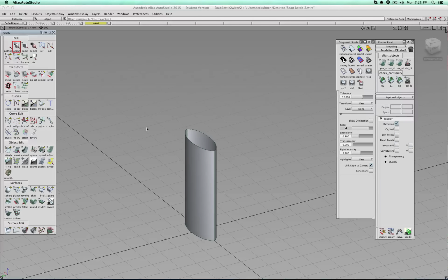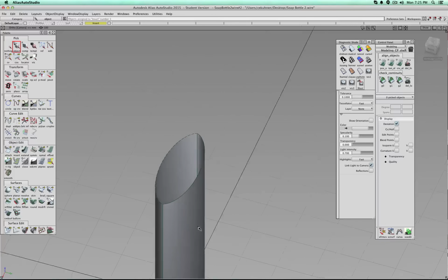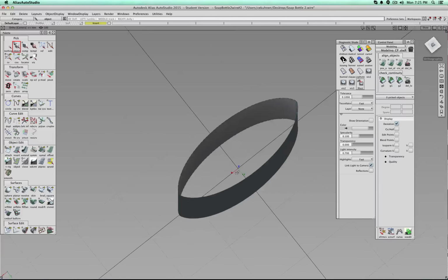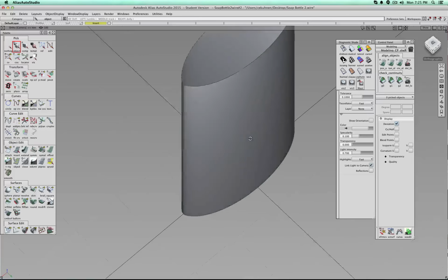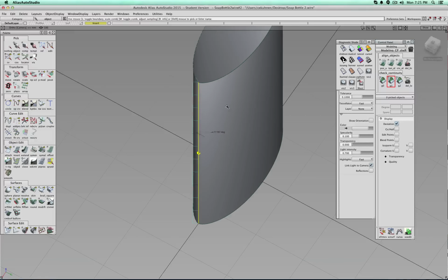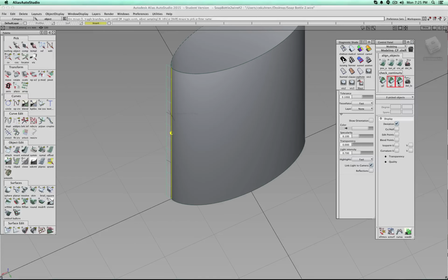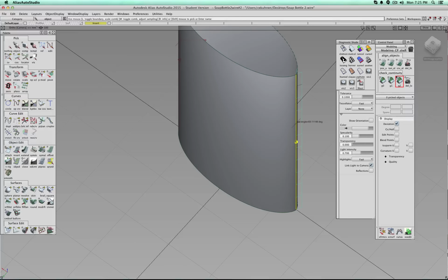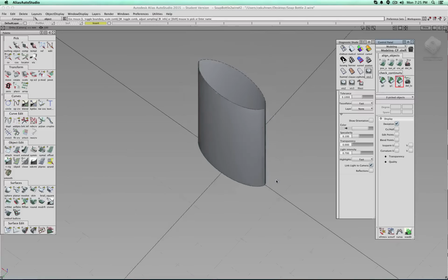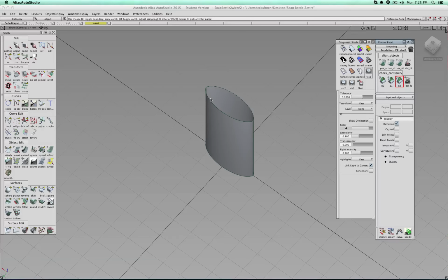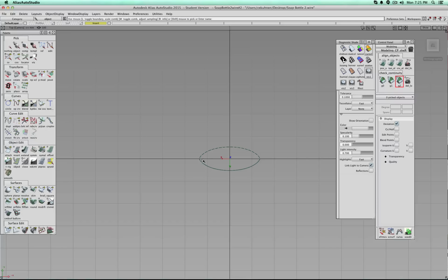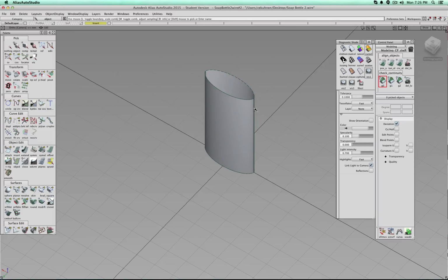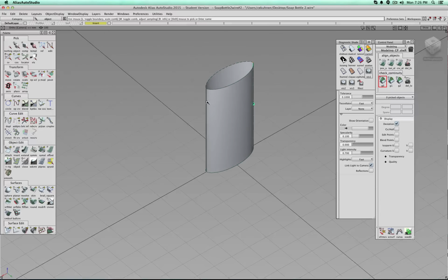Let's actually turn on symmetry, and here you see another problem. It is very pinched. So if we check, tangency is yellow, doesn't work. G2 anyway. So doesn't work. And the problem is basically the offset broke the continuity. The edges meet perfectly, I think. Let's see. Yeah, see, so positional works, but that's not what we want. So how do we fix this? Well, this is pretty simple.